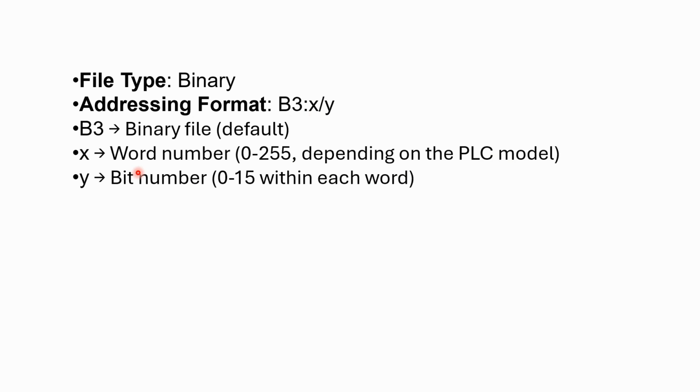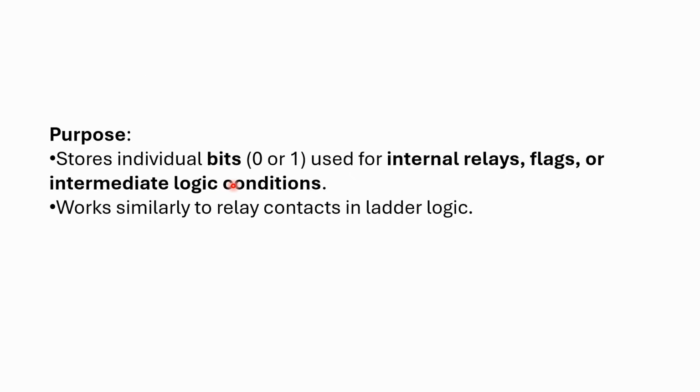The Y at the end represents the bit number, and that's going to be 0 to 15 within each word. The purpose of these really is just to store individual bits, either a 0 or a 1. These are used in programs for things like internal relays, flags, or intermediate logic conditions. It works very similarly to relay contacts within ladder logic. And the big thing is to remember the binary files, the B3s, are internal relays. They're not real world outputs like the O addresses.